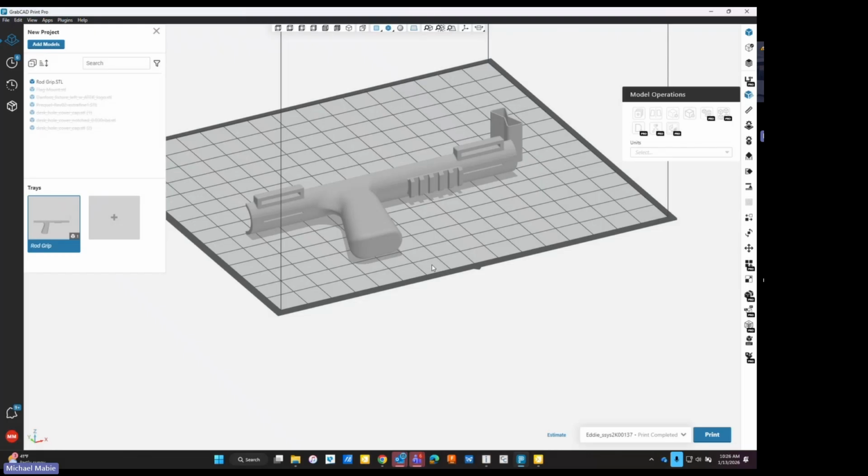So what you can do is use Insight, and you can go in and modify chunks of support material in approximately a 3-inch span. That way you maintain your accuracy for your part, and you're not introducing any potential build issues with your support being at an incorrect height for the model. And that's one of those things that I plan to cover in a future session, using custom groups within Insight to make some tweaks to the support structure.